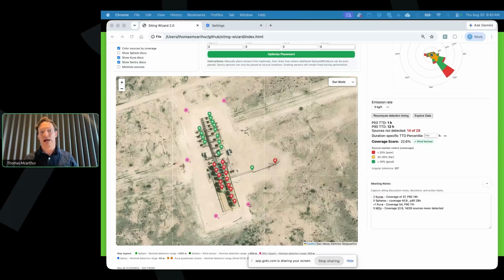We do apply specific venting, permitted to emit thresholds for each source. Once you do a deployment and you have a CS deployment, what you can do is you set a threshold for when you want to be made aware of certain emissions, and you set a threshold for each source to say, well, we know this is a venting source, so we can set that to whatever, 1 cubic meter per day.